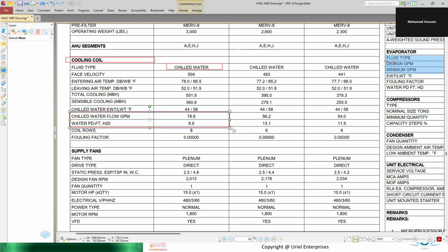The pipe size actually. How much line size, how much pipe size is going into the coil. We need that information, because using the GPM and pressure we can calculate, but in the catalog we have to locate the valve pipe size also and match it. For example, if the pipe size is given as 3 inches or 5 inches, and we choose according to the calculations 2 inches, there will be a 3-inch difference between pipe size and valve size.